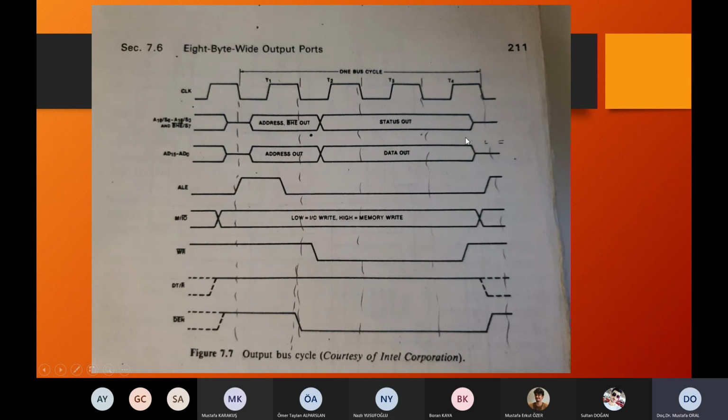So, or something is wrong with the device. If it cannot present the data directly, the microprocessor has to wait until the operation has been completed. So it inserts wait states, it inserts waiting clocks inside. I mean, it has to wait there.